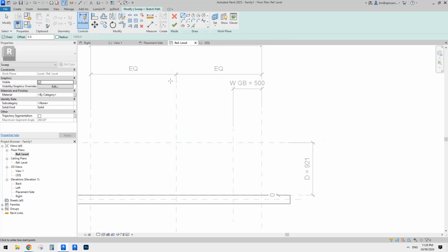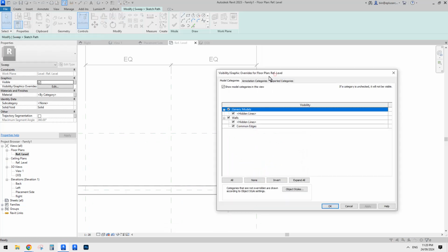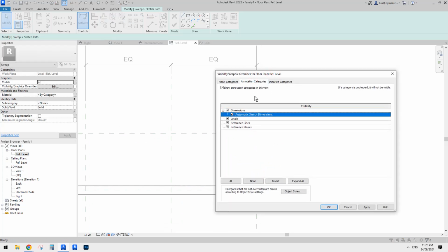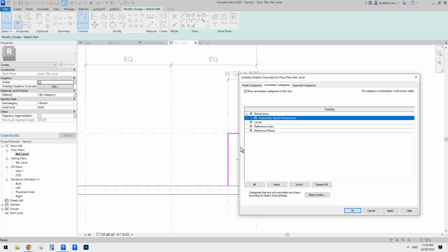Okay, so for a sweep, I'll use sketch path, and I'll use set work plane. The default will be a reference level. That's fine. I'll just draw a line and lock. I'll just maybe pick line, lock. Yeah, so you can also directly draw and then lock them afterwards, something like this. And also type VV, so this will help us to see whether they are locked properly.